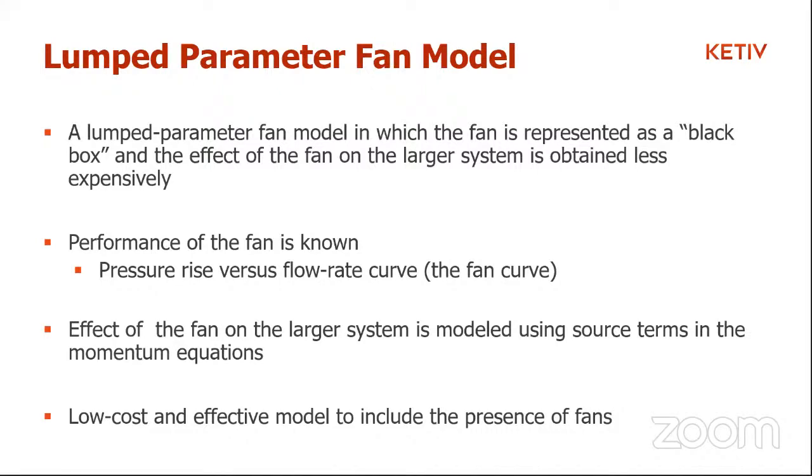This is a very simplified way of setting up a fan model. But if you have a lot of fans in your domain, for example, you're doing an entire building analysis and you have 30-40 fans, then for those situations, this sort of a fan model works well, because you're basically specifying a momentum source and you're specifying a pressure restriction, and that gives you the same sort of effect as modeling an actual fan.